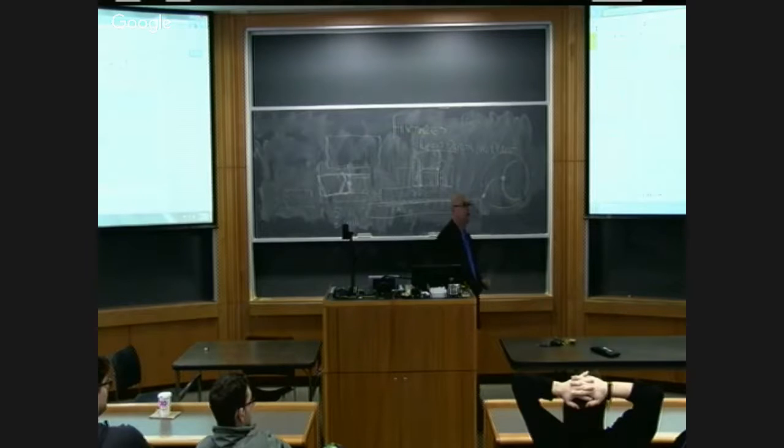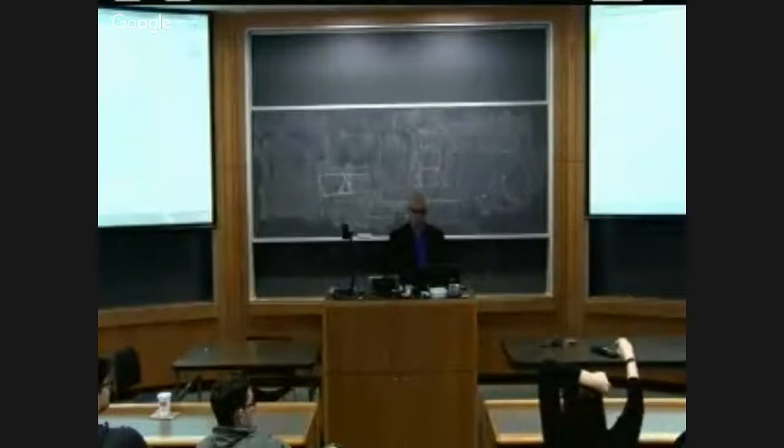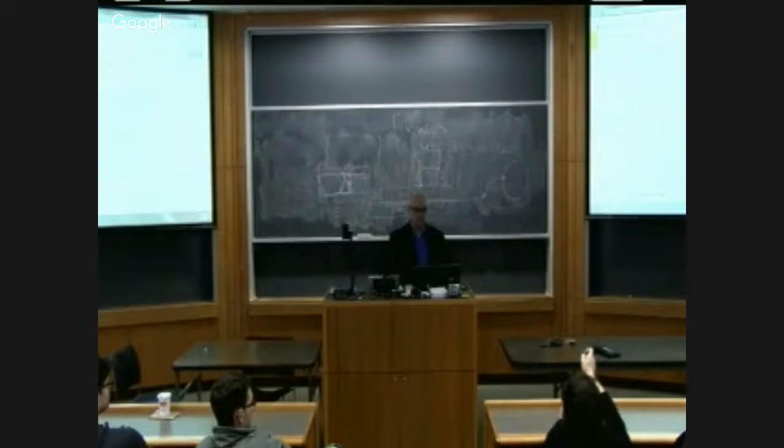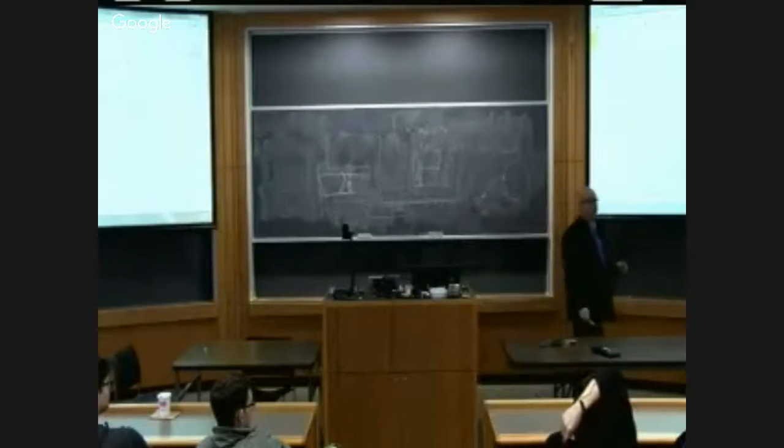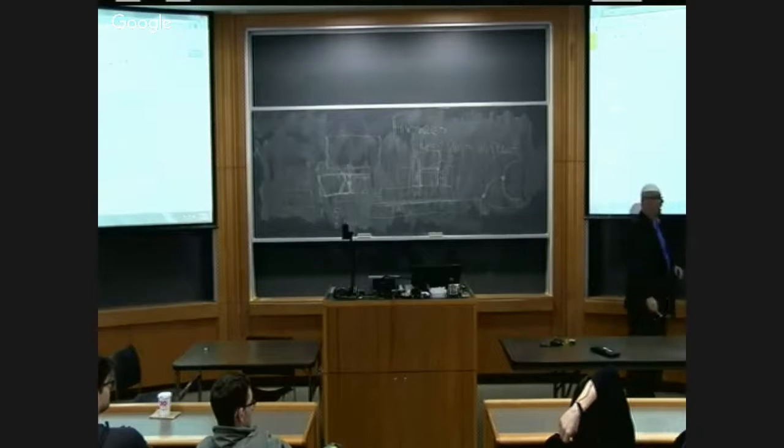So if I tell you that's roughly what my stock looks like and this is what the part looks like, how would you start? I might start by putting that silhouette into the top of the part, without going all the way through the width of the part. That would be really good. If my stock material is plenty thick, we define a pocketing operation where this is an island that sticks out of the pocketing operation. We remove all the material and make a plane below it, and our part is now sticking up out of that plane as a boss.